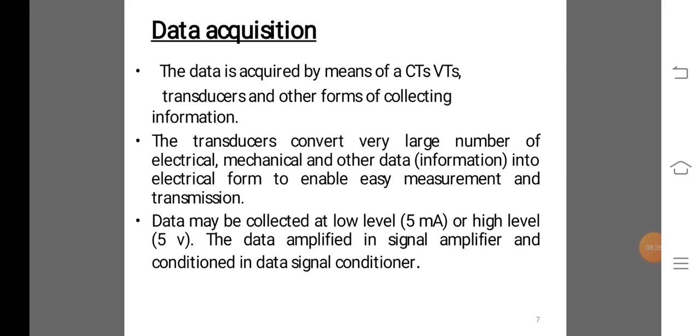The relays located within the RTU, on command from the ECC, open or close selected control circuits to perform a supervisory action. Such action may include, for example, opening or closing of a circuit breaker, modifying a transformer tap setting, raising or lowering a generator megawatt output or terminal voltage.